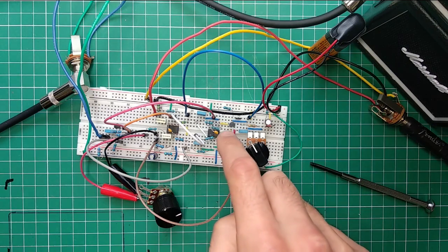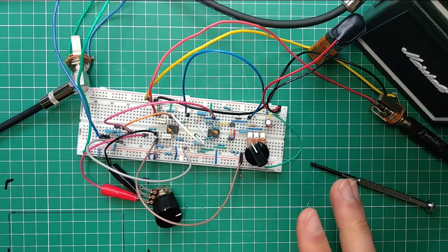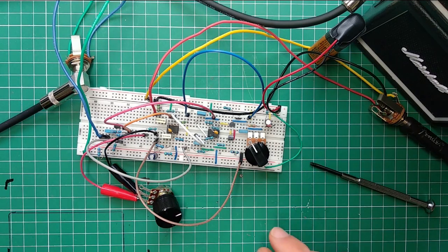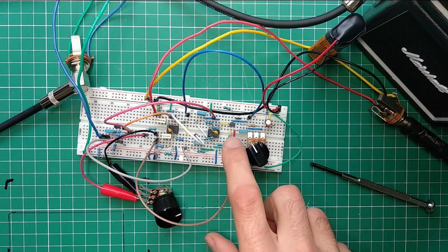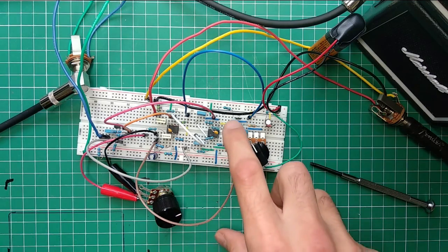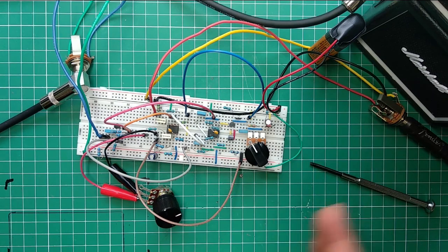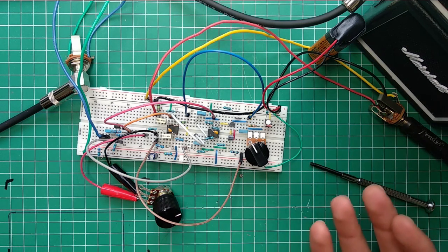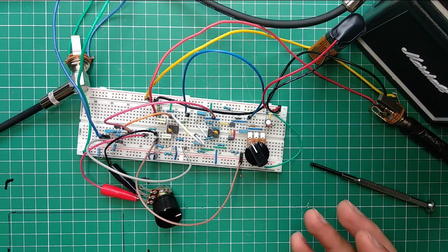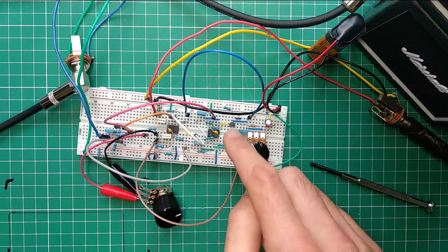Now one thing that I did not do is I did not pair these JFETs. That is something to do. But if you remember, it will work, because if they don't have the same kind of resistance change, let's call it that way, we maybe won't get as dramatic a change or as good of a sweep.